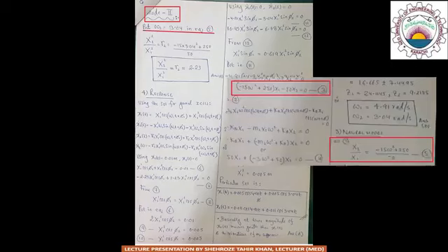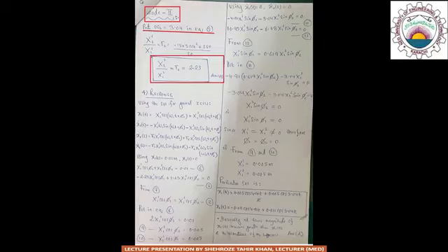So for the ratios of the second mode of vibration, the second natural frequency, that is omega 2 equal to 3.04 radian per second, is substituted in the modified form of equation 3, that is equation 5, and we get x22 upon x21 is equal to r2 is equal to 2.23, where x22 is the natural mode of vibration of the second mass, which is the suspended mass at the second natural frequency, and x21 is the natural mode of vibration of the first mass, which is in this case the optical table at the second natural frequency, and the positive sign indicates that these two are in phase with each other.